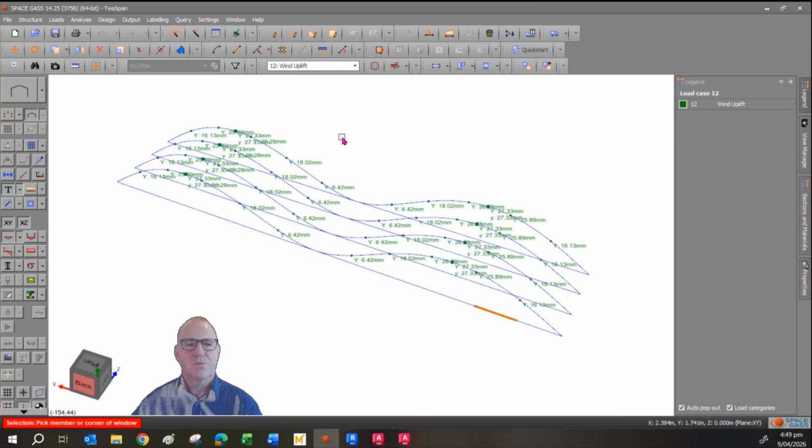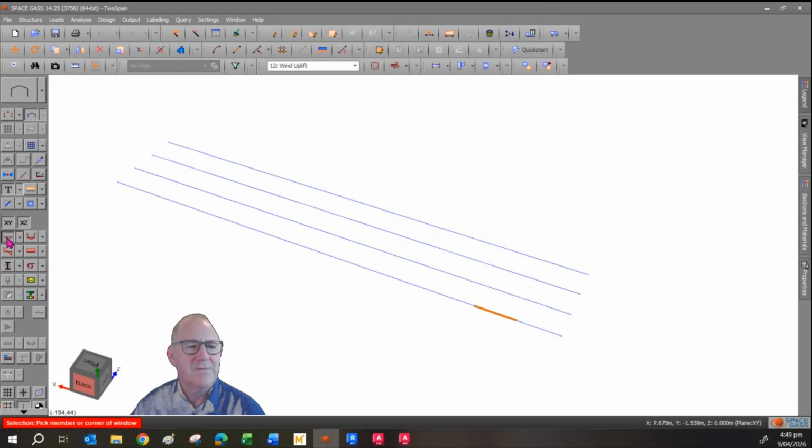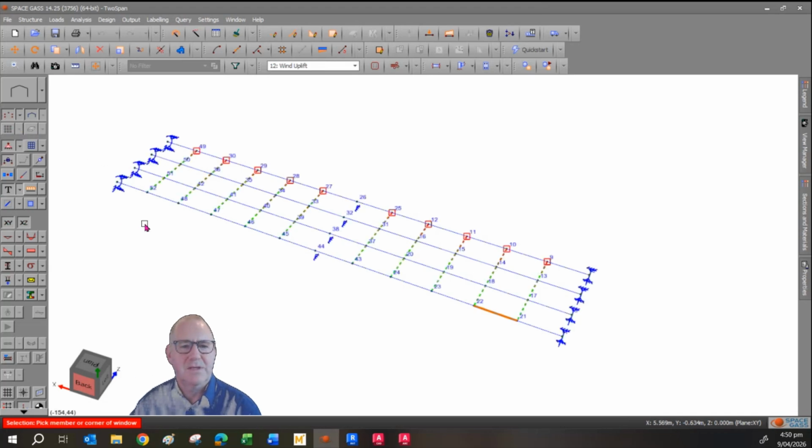Okay, so that is the wireframe model. You're probably wondering why I've done so many nodes. It, of course, is to keep the shape together. But if these were individual beams, you wouldn't get the deformation because they'd all deform individually as individual beams. So the way to make the beams work together is to use the master and slave node options.